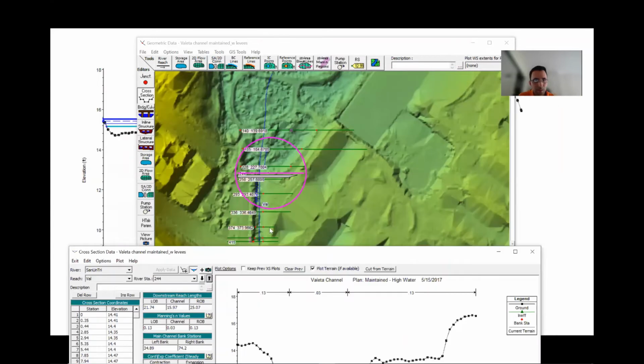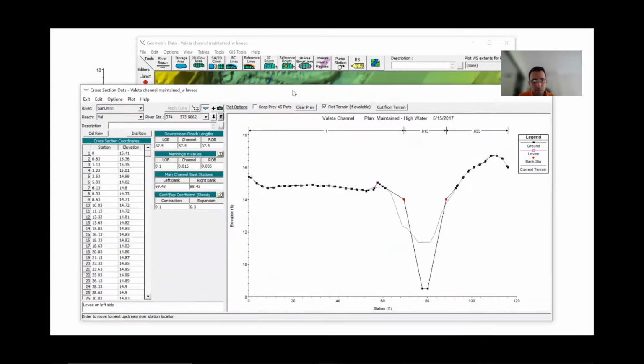Like this guy, let me show because it's nice and round. Okay, so what I've done for this one is basically, you can see only with these 4 points, I can create the shape of the trapezoid as I was showing you in the first video. And of course, these are just station elevation. You want to make sure that when you get to this station, you go to the next one, you maintain the side slope.